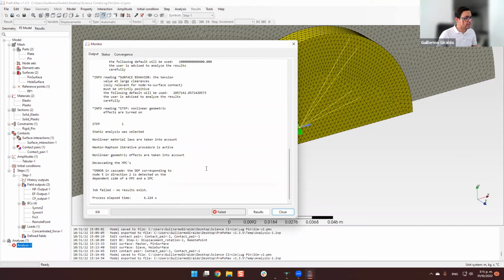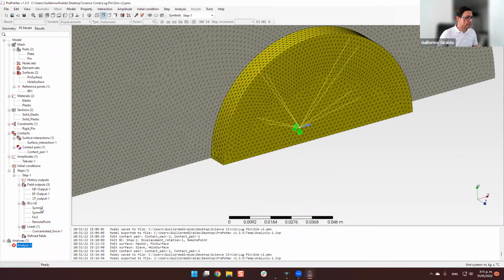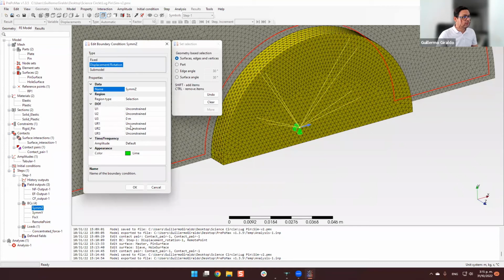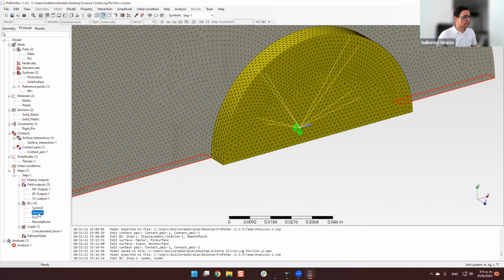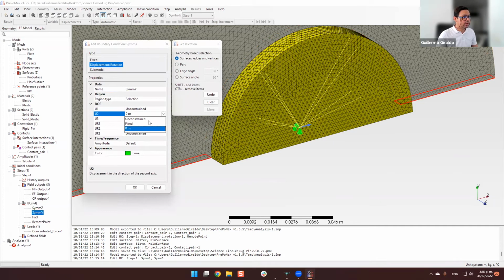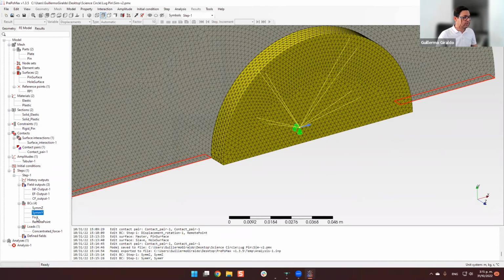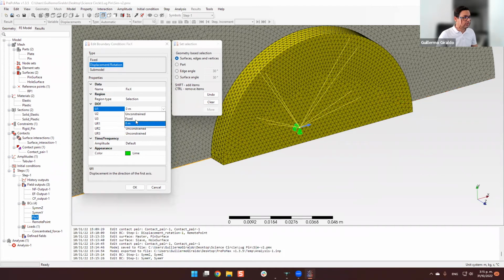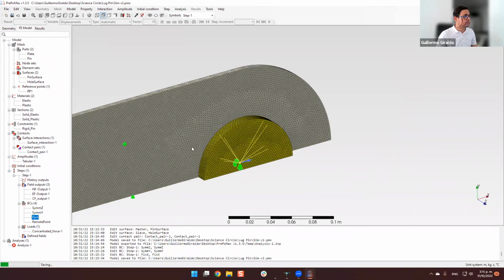Yes, it failed again and it says the same error, which is weird. Let's say that this is fixed instead of 0, because it can be that by making it 0, it's not using elimination, but it is using a Lagrange multiplier, which is another concept, and that might be what is causing the over constraint.